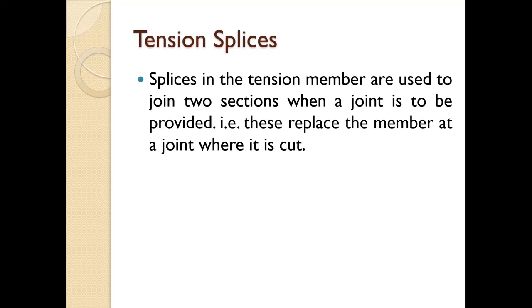The force is then carried through these covers across the joint and then transferred to the other portion of the section through the connection. The splice section as well as the rivets are designed for the tensile load to be transmitted by the main tension member. There is always a question whether the splice should be designed for the maximum calculated force or the actual strength of the member.